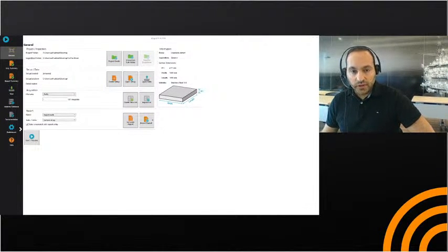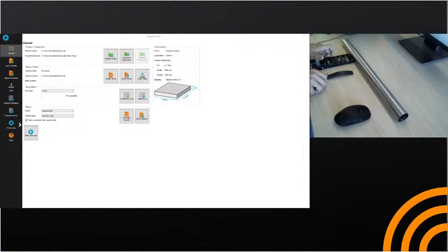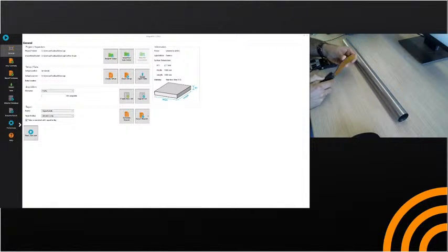Let me show you what I brought with me. So here I have the iFlex. This is our iFlex probe, small version. It's our high resolution iFlex probe. It has 34 millimeter of coverage, and it contains sensors or coils about 2 millimeter OD.